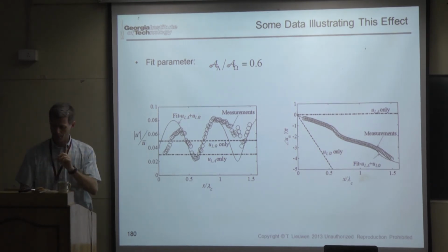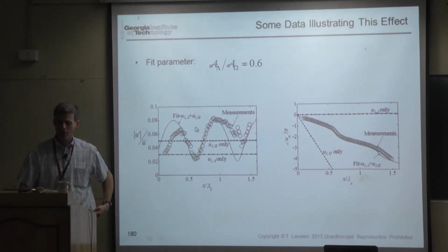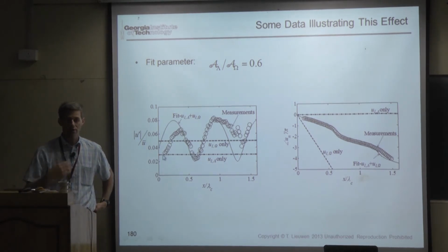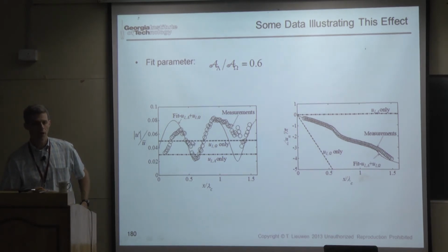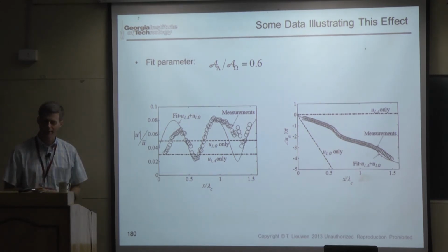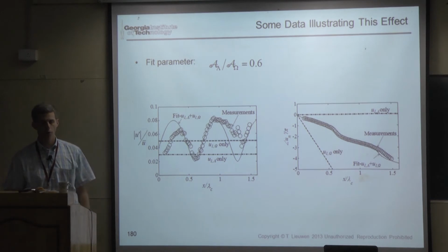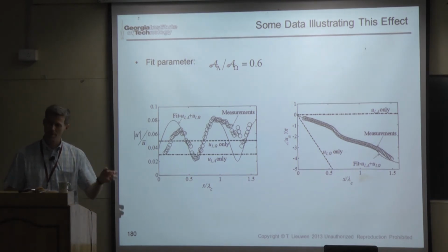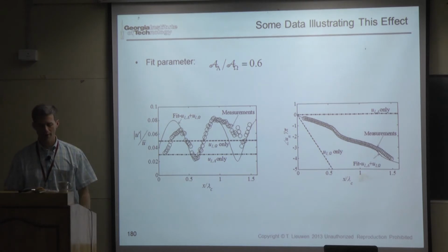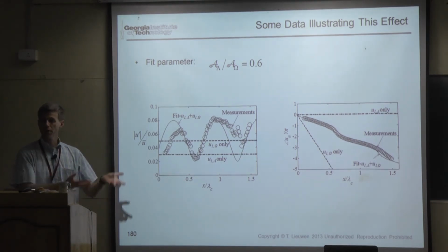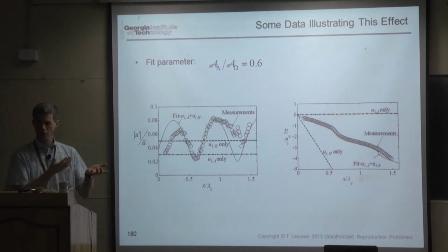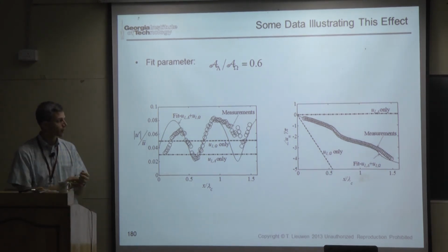It would be wonderful if we could actually do these decompositions on data, if you could actually decompose the velocity into the acoustic and the vortical component. It's really hard, right? The vortical part is going to be related to the, first of all, you're going to be differentiating data, and then it's a complicated operation. Some people have done it on numerical data where they take a DNS or an LES, and then they will decompose the disturbances into their acoustic and vortical and entropy part. And it's very illustrative. Yes?